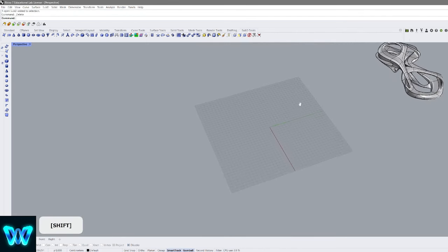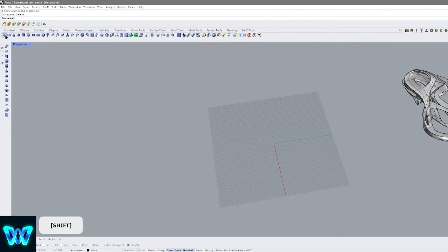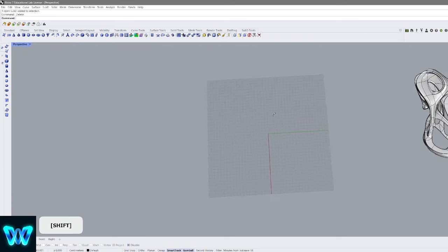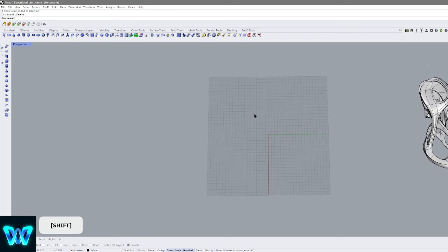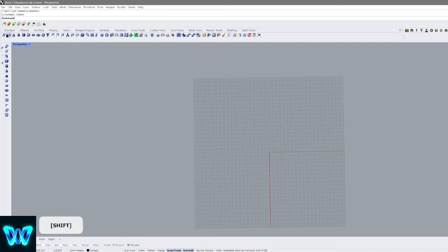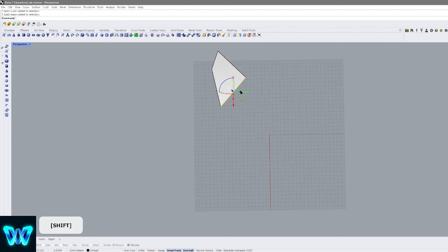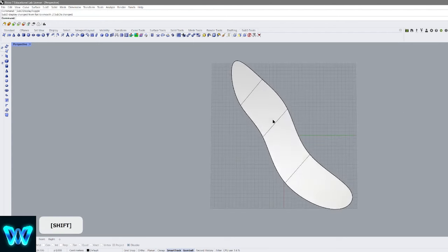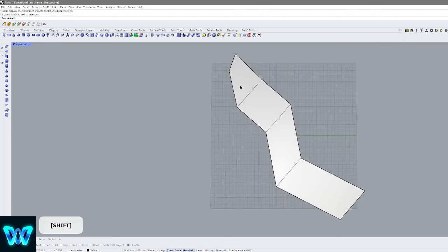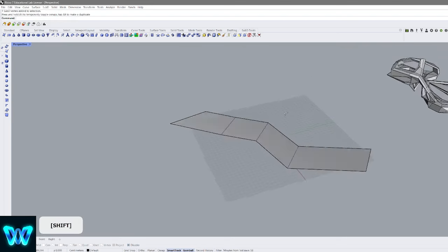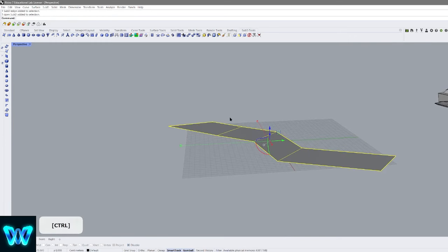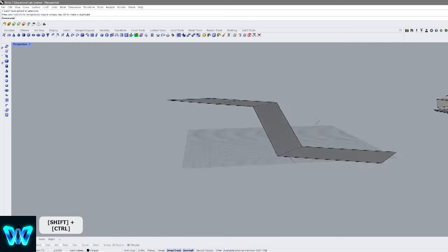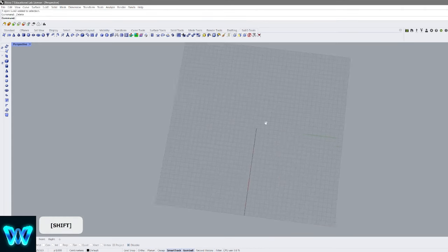A good way to model in SubD is to start flat. So in these two cases, these are really good tools, because you can start flat, put an image under this, and just start tracing and slowly create what you're trying to do. In this case, we can start moving and start creating this sort of snake-like thing. Then you start to add detail in this SubD right here. And after you have the detail that you want, then you start creating the depth that's necessary for your model, right? So that's a good technique.